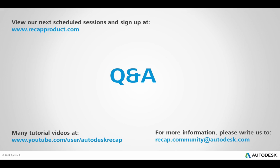Another thing to keep in mind regarding performance is where the data is located. If the data is located on a network server, for example, you can experience some latency. If there's a lot of traffic on the network and you're trying to visualize that data and pull it over the network into Navisworks, you can experience some issues there. So I recommend having a local copy of the laser scan data, especially if you're dealing with large data sets. 400 scans, that's a pretty good size job. I've seen upwards of 2,000 scans, but these data sets can be many gigabytes in size, and so if you're pulling that data over a network, you can experience some latency.